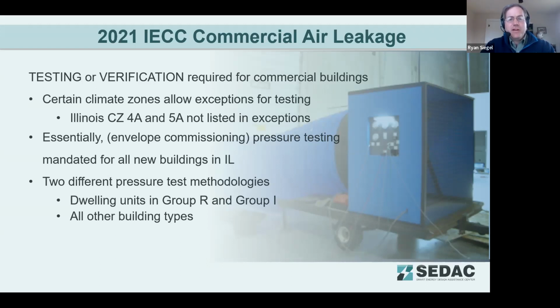But testing and verification is going to be required for commercial buildings. There are certain exceptions listed in the 2021 IECC, or International Energy Conservation Code. However, climate zones 4A and 5A, which is where Illinois is, are not listed anywhere in those exceptions.